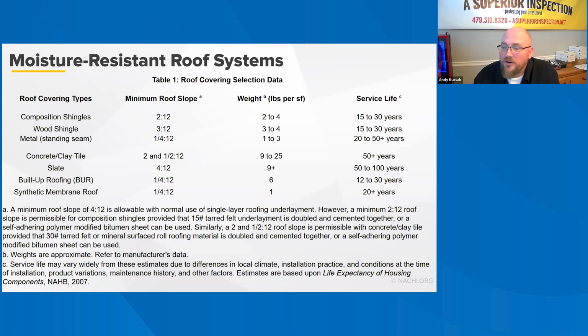Optimal slope of a water shedding roof. Considering several factors, a moderate roof slope of from 4:12 to 7:12 provides a favorable balance of pros and cons for water shedding systems. For example, lower roof slopes will tend to decrease drainage efficiency, allowing debris to accumulate and increase wind uplift loads on the roof. In addition, as the roof ages or becomes damaged, leaks are likely to be more severe.